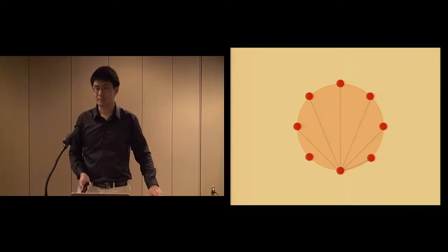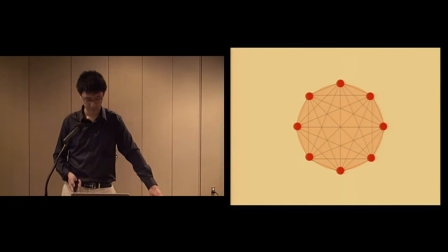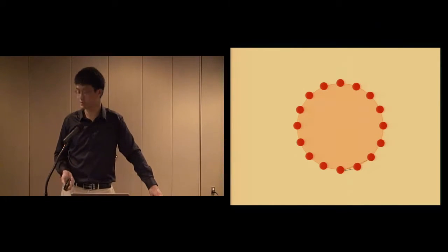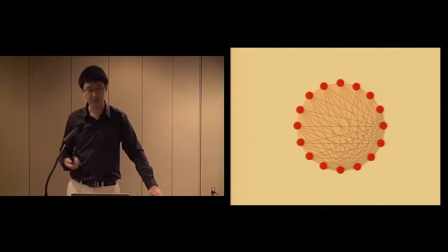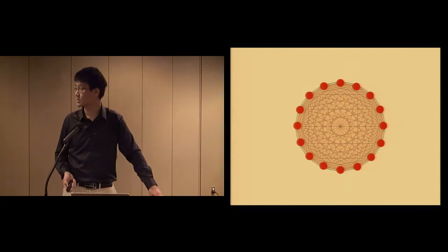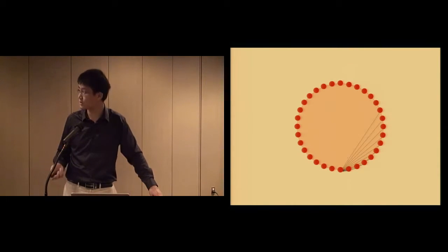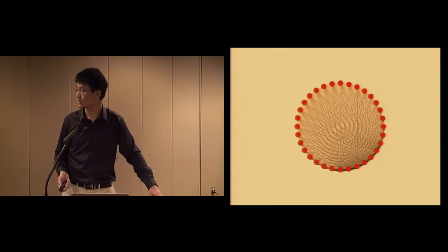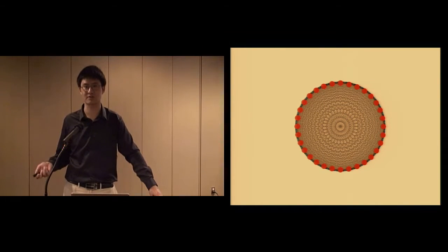So in addition to the sensing mode, we can also adjust the number of electrodes. Tomo used 8 electrodes, as you can see here, the sensing paths shown. When we go up to 16 electrodes, we will increase the number of sensing pairs and therefore the resolution. But the big trade-off is that we're going to have to spend longer doing all the measurements. Taken to an extreme in our case, we can go up to 32 electrodes. You see there's a lot of sensing pairs and also correspondingly a much, much higher resolution. So with this kind of setup, we can get a very high resolution picture of the internals of the arm.